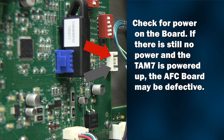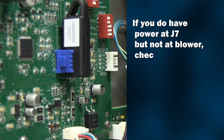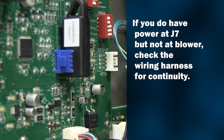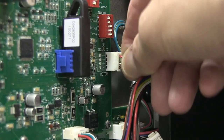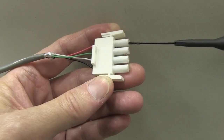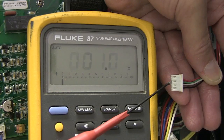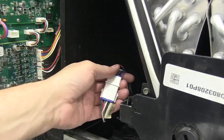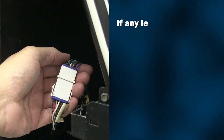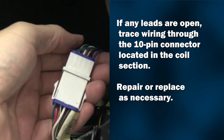If you still do not have power and the TAM7 is powered up with the LEDs on, the AFC board may be defective. If you do have power on the AFC board but not at the blower, check continuity of the wiring harness by removing the connectors at both ends and ohm the leads. Go ahead and check the continuity of all 4 leads, the red, green, white, and black leads. If any of the leads are open, trace the wiring through the 10-pin connector located in the coil section of the unit and repair or replace as necessary.